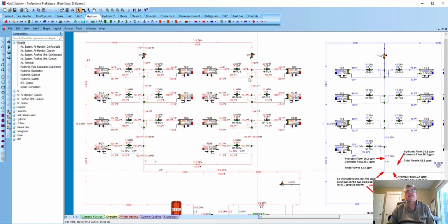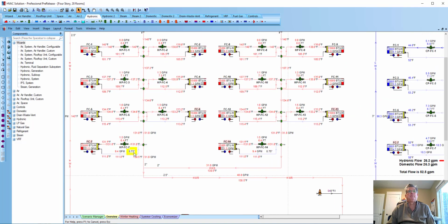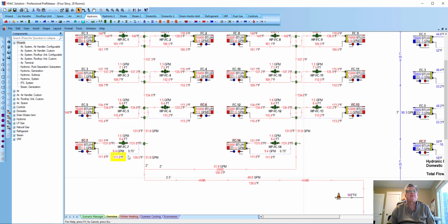So these cascading temperatures are going to mix and only allow, like we said, that we set the entering and leaving temperatures of the boiler, which sets that flow around the system, so you're always going to have enough hot water. You'll see the little blue line down here. That's just saying, hey, your water's getting a little bit colder. When it gets down to around 100, I think 112, we set the temperature to turn the piping color to a blue, so you kind of know that.